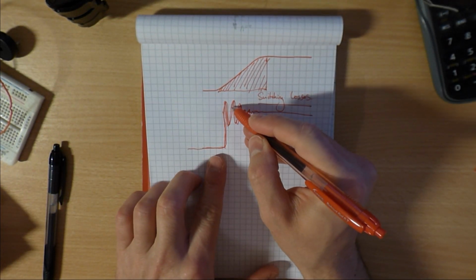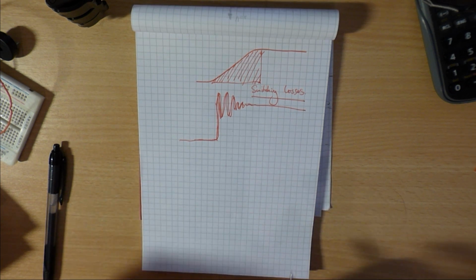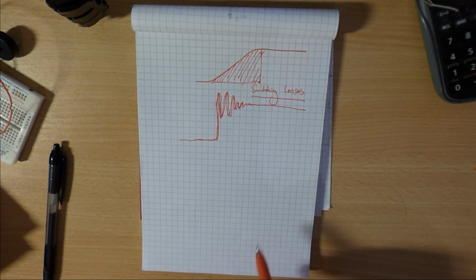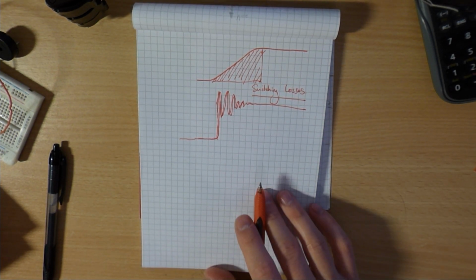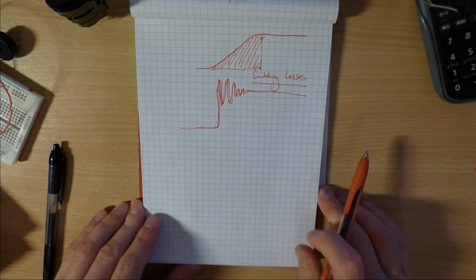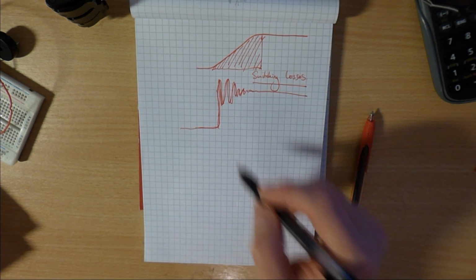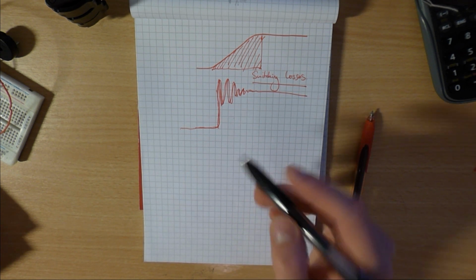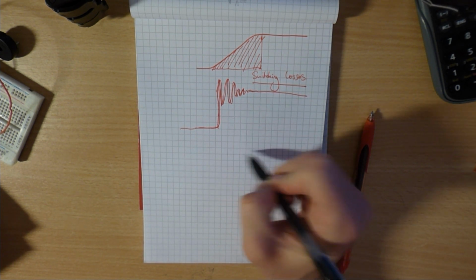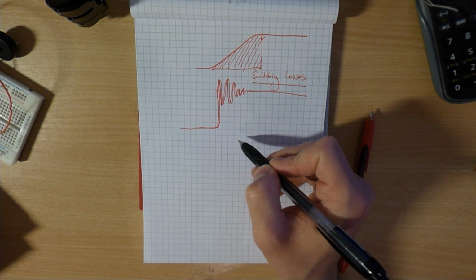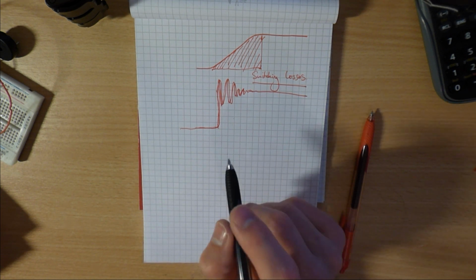Another thing that will help the ringing is turning it on slower. The way that we can do that is with a gate resistor. But that aside, those are just a couple of things that I wanted to mention. The IR2110 has a totem pole arrangement within it, which is what does the switching between the bootstrap capacitors and the H out.